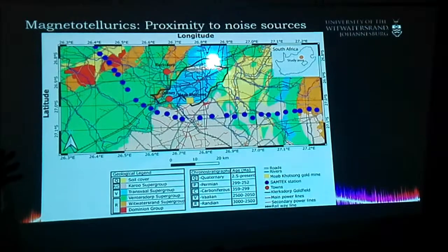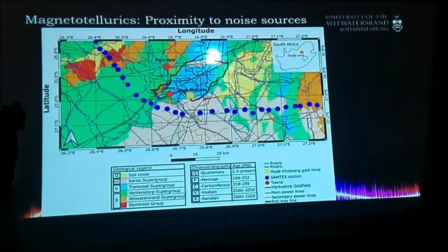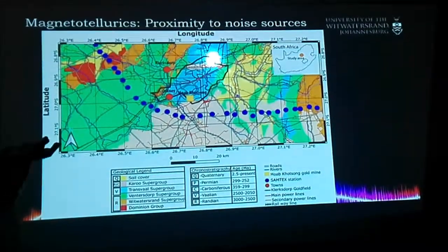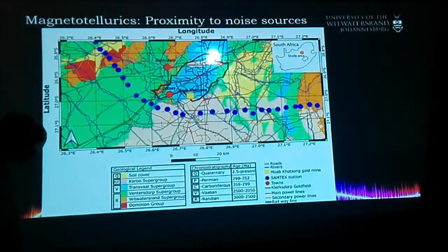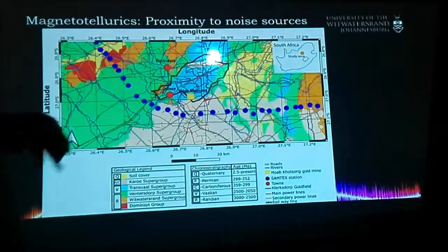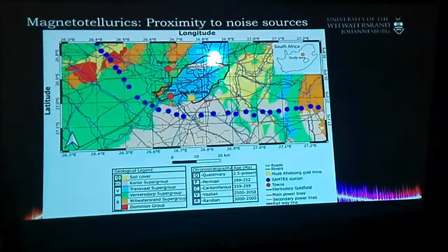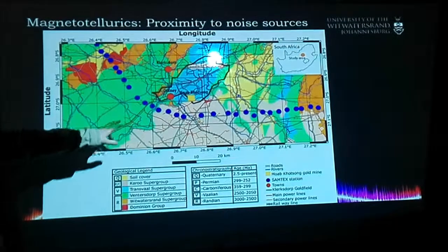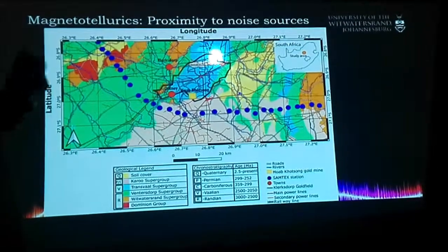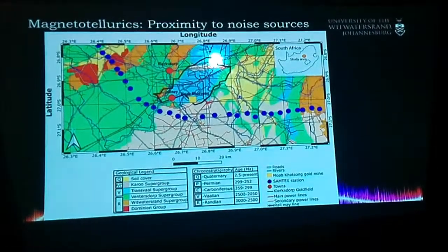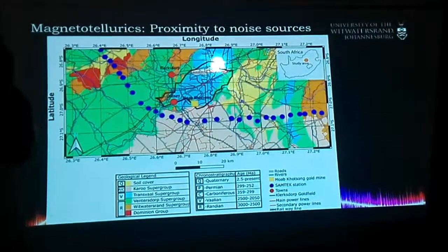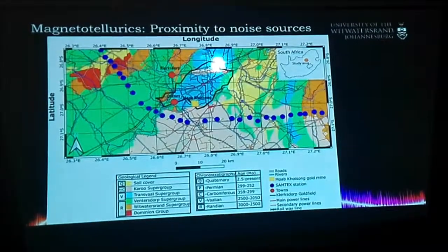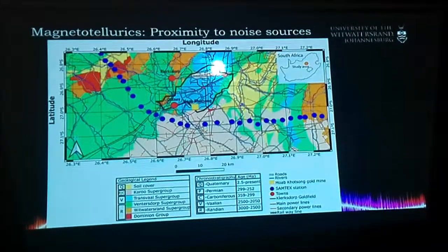Something interesting: the worst noise-introducing system is agricultural equipment. The crop irrigation systems, those ring systems, those circles, are the worst. They leak so much current. They're worse than these railway lines. If you're near one of these crop circles and they are irrigated, you're not going to get any signal. It's just going to be sporadic, because they've got no control of the frequency, so it's just dumping current into the ground. So that's something to keep in mind when on these farms, if they're irrigating something.